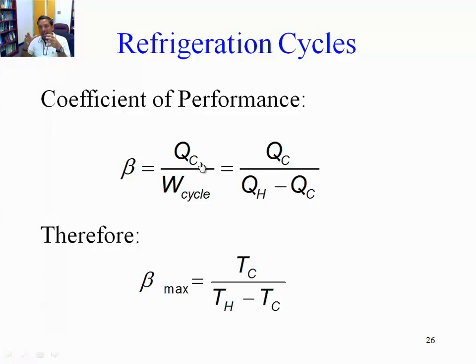So my room is acting as a cold temperature reservoir, and the refrigeration cycle going on, which is some refrigeration system sitting somewhere, with some pipes going through my room, extracts energy from this room and then rejects energy to the hot temperature reservoir. So it does the opposite. It subtracts energy from the cold temperature reservoir and it dumps or rejects energy to the surroundings. And it does so by using work. So this is the opposite. We are transforming mechanical work into heat.